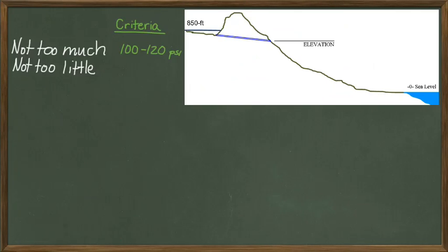Even though each agency can decide the minimum and maximum pressure, there are typical values used by most agencies. Most set the maximum static criteria between 100 and 120 psi, while on the low end, values between 45 and 60 psi are typical. Given the elevation of a water source, there is a maximum and minimum elevation that can be serviced so that the pressure stays within the static pressure limits.